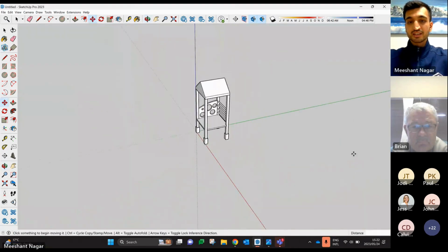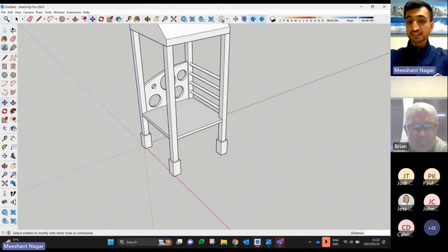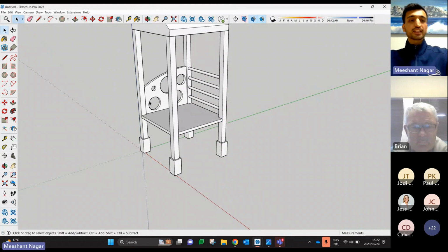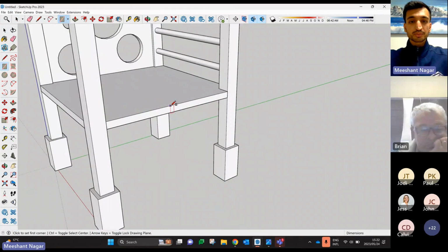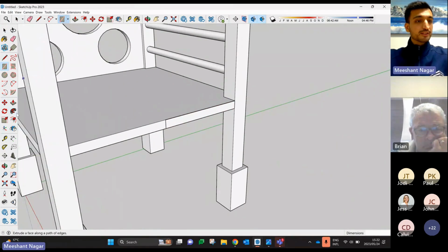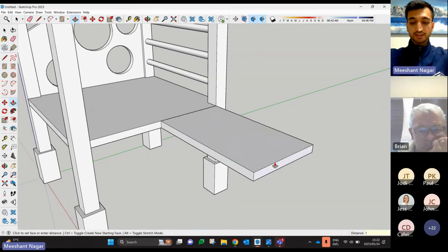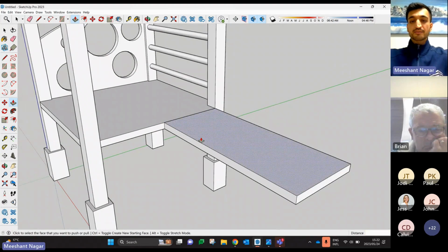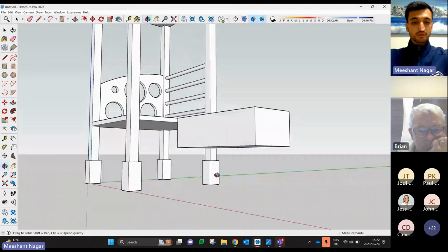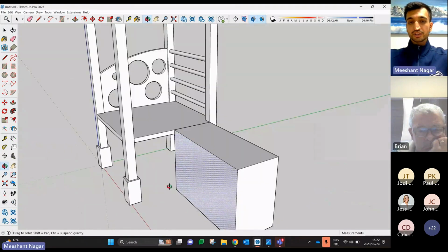Okay. Moving on to the next side, I think on this side, what we can do is create a stair. So to create a stair, once again, using the rectangle tool, I'm just going to be selecting onto the midpoint of here, into there. Using push pull, I'm going to drag this out, let's say 1,200. Enter. And then I'm going to drag it to the floor using inferences to the bottom of the pile. And there we have a shape.